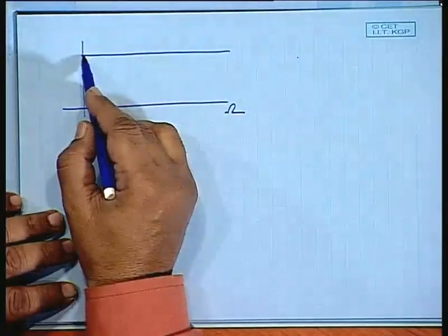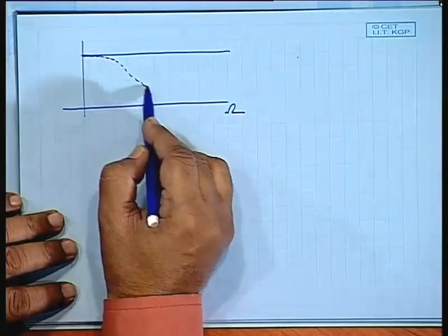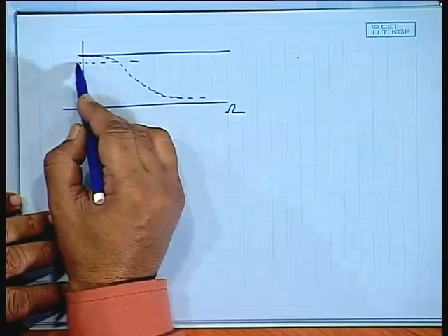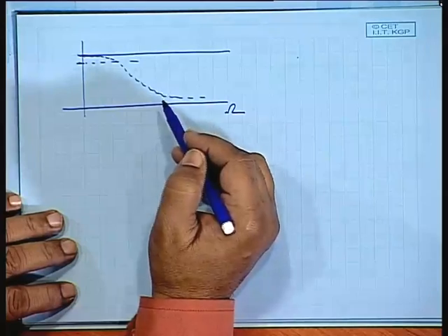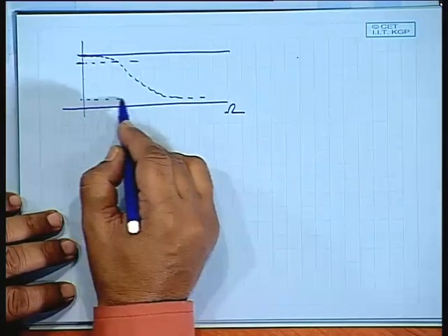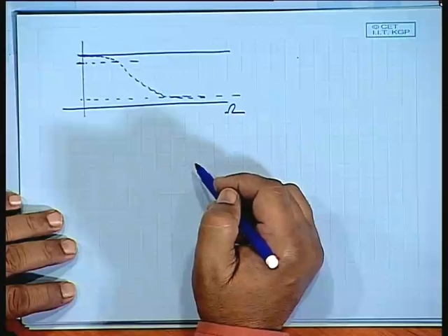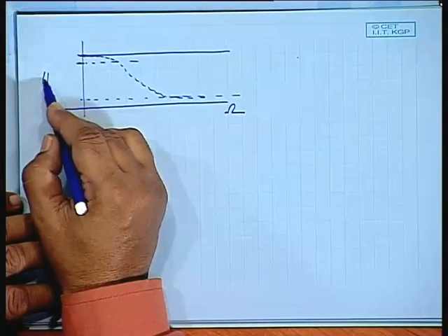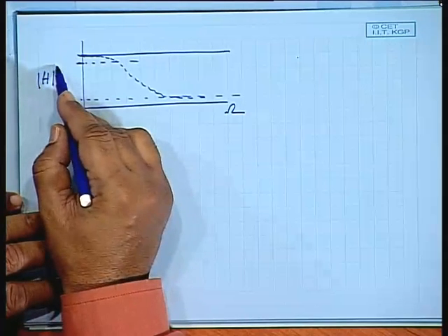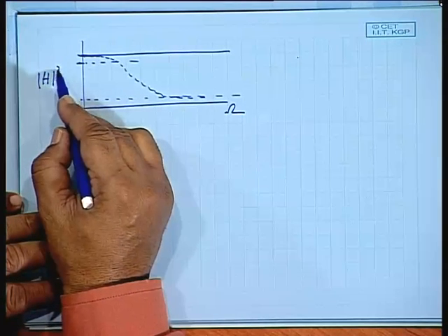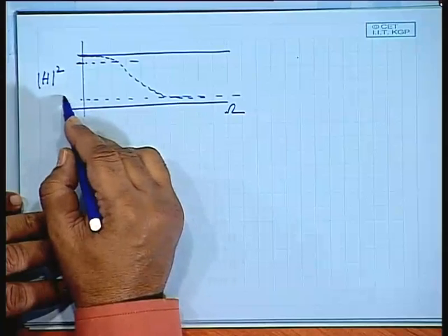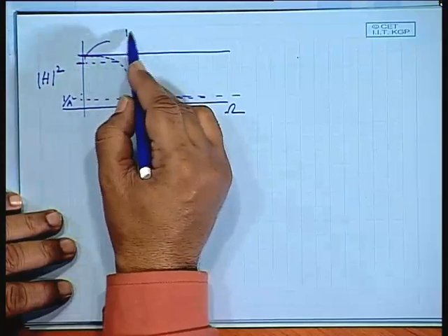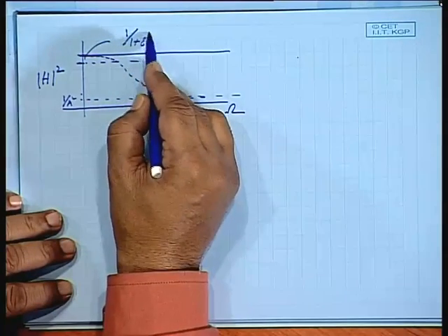As I was mentioning the other day, a low pass filter for example will be specified in terms of some tolerance in the pass band and something in the stop band. So, this we are referring to, say if it is h magnitude squared, then this was 1 by A squared and this was 1 by 1 plus epsilon squared.